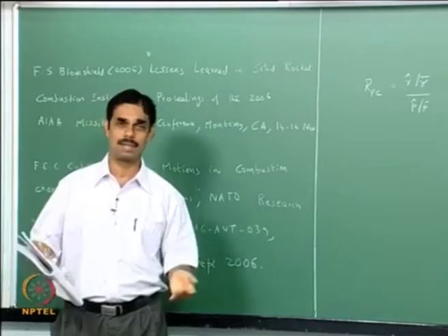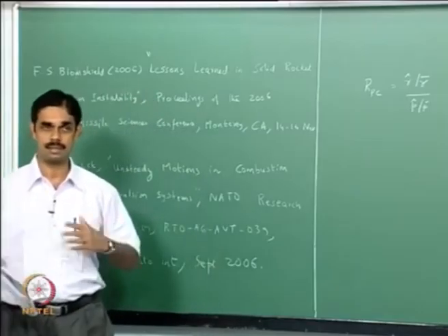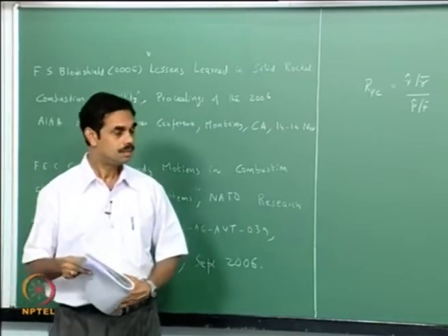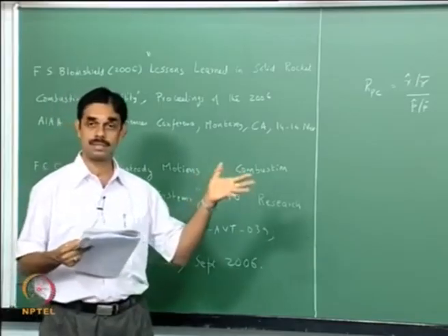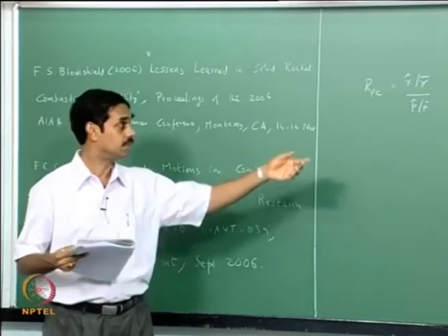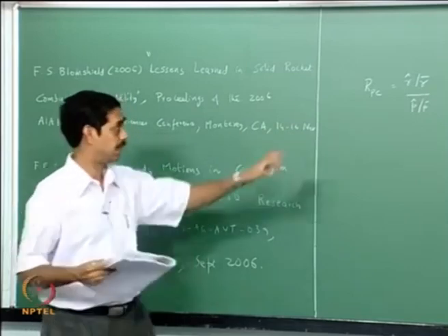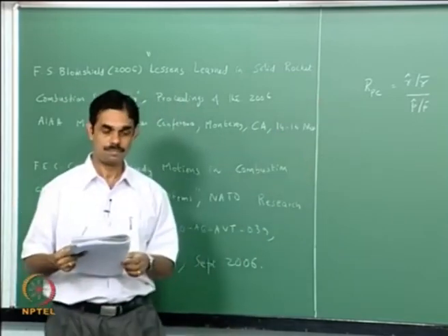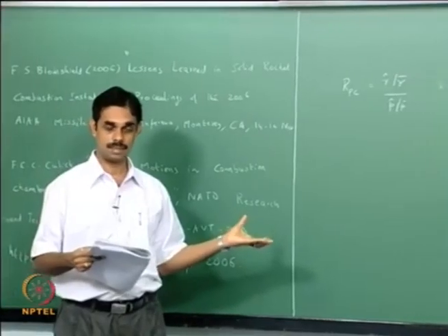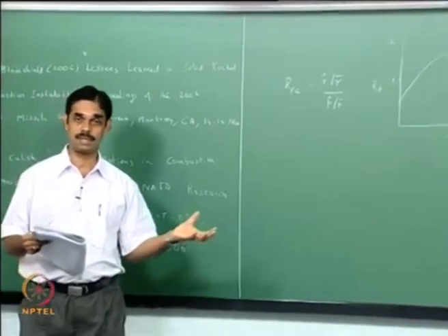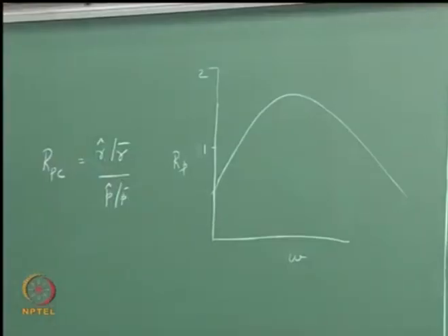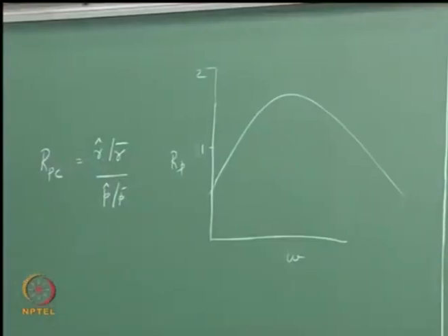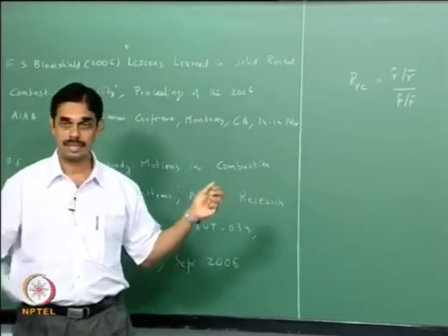In general all propellants drive, it is very unlikely that propellants will damp, and we should use this in the calculation of alpha from the pressure coupled response. That is the primary driving mechanism, and the issue is whether that can be balanced by our losses.